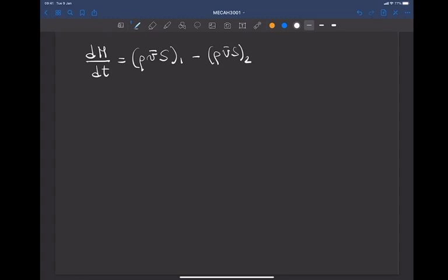And of course here we are considering the average velocities on the section S, and we consider the scalar value of the velocity because this is a scalar balance. Of course, from this general equation, you also realize that in case the problem is steady, this term is equal to 0, and then you would recover the steady balance, which is mass flow rate at section 1 equal mass flow rate at section 2.